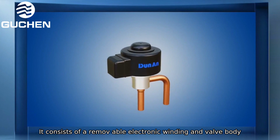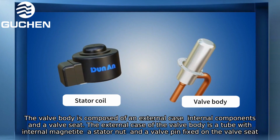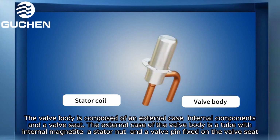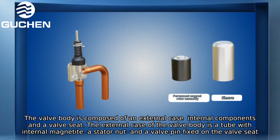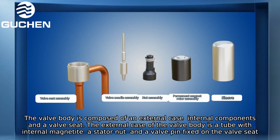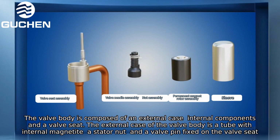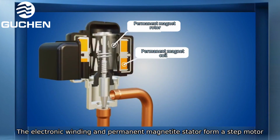It consists of a removable electronic winding and a valve body. The valve body is composed of an external case, internal components, and a valve seat. The external case of the valve body is a tube with an internal magnet, a stator nut, and a valve pin fixed on the valve seat. The electronic winding and permanent magnet stator form a step motor.